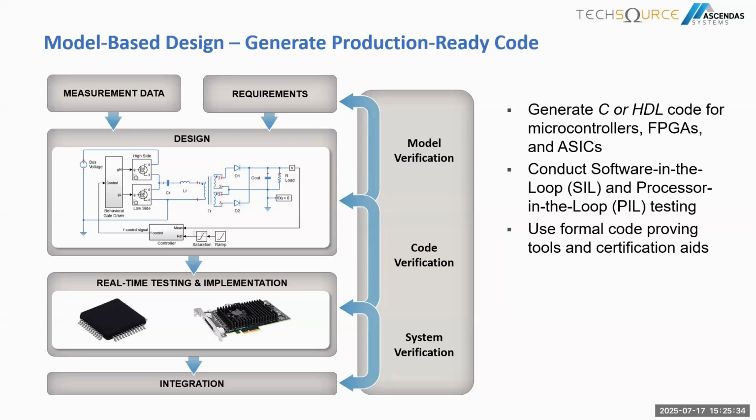So these are able to generate your code at the same time and put it in a microprocessor, for example, and then you are able to check the responses of your system. So Simulink will step the processor for each time step, collect the output data, compare the differences, and again verify the numerical equivalency of the control algorithms.